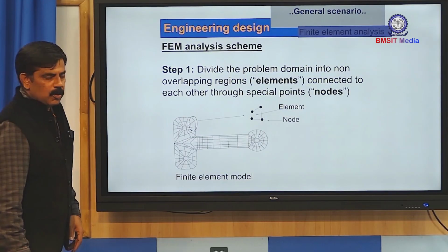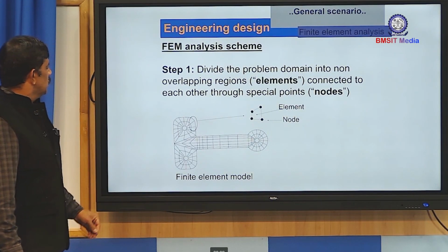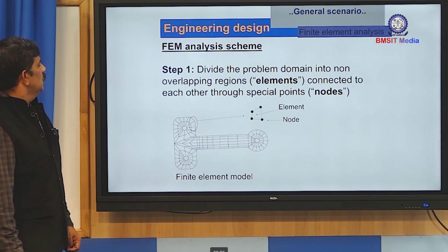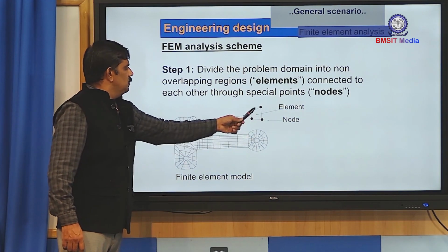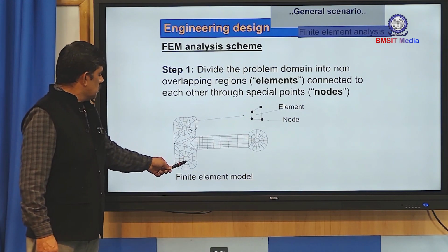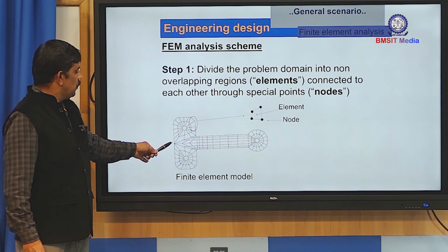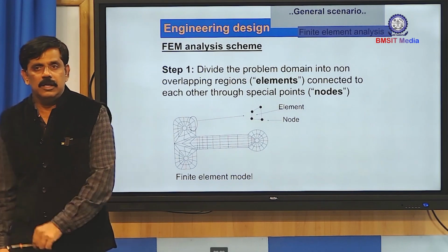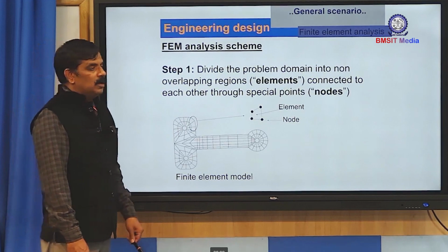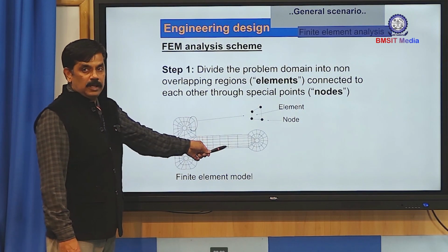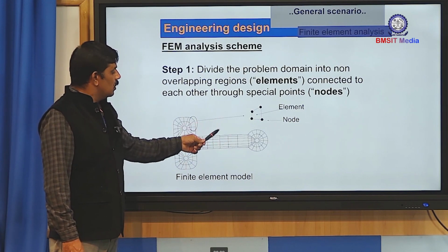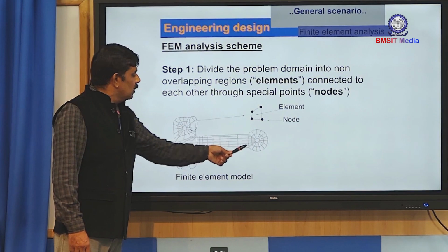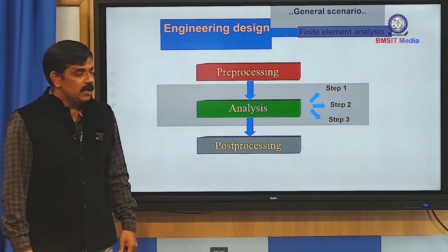This is the same example we can see. So we have the 2D component. The component is discretized, and we can see the quadrilateral element in our case. This is the node, and this is the element, a quadrilateral element. There may be some parts where there is a triangular element also, depending upon the spacing available and where exactly the stresses are induced. There may be some stress concentrated area. In those stress concentrated areas, we have to go for finer and finer meshes. But if there are no stresses in an area, then we can go for the coarser or bigger mesh size elements. But wherever there is a stress concentrated area, in such cases we can go for finer and finer elements.